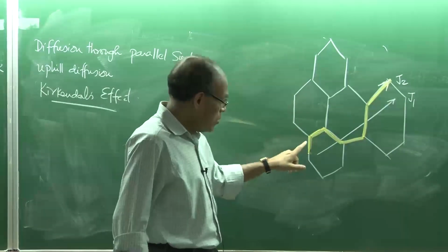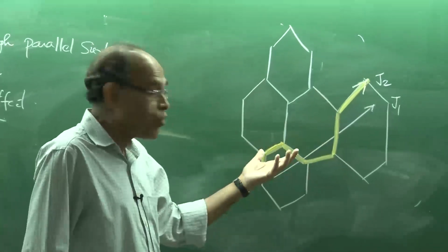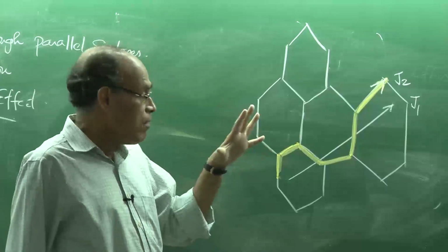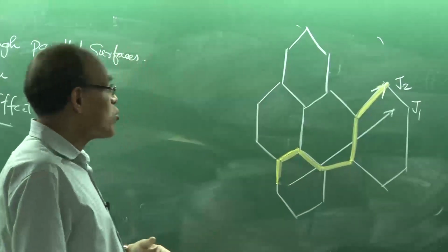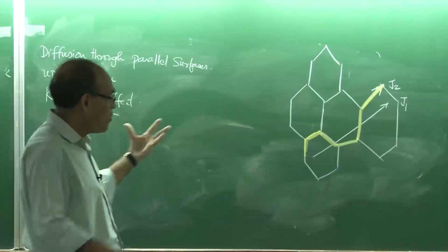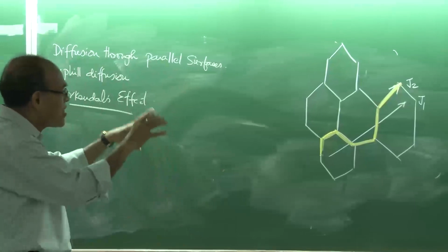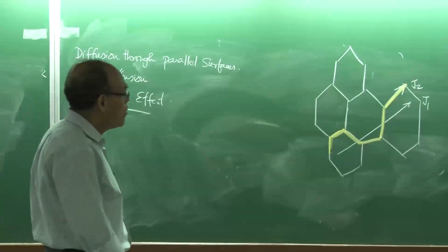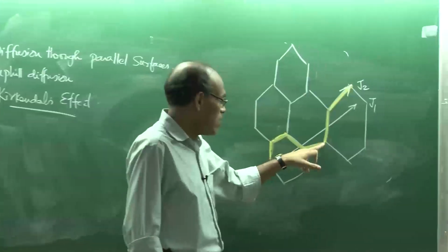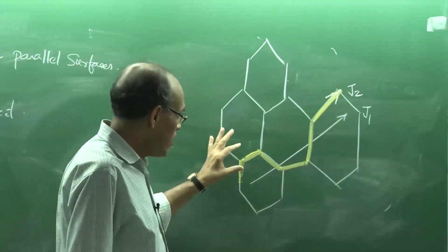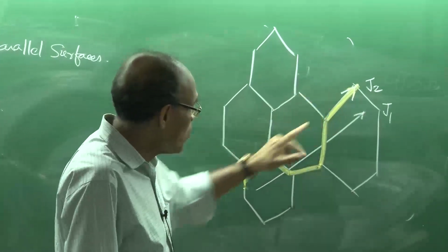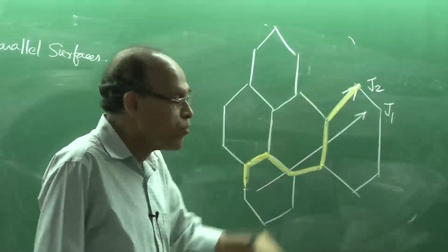Now, the grain boundaries, as you all know, contain defects, and we know that diffusion is promoted because of defects. We have interstitial defects, vacancies, etc., which promote it. Had the material been perfect, with every lattice site occupied, there would have been virtually no diffusion at all. So, because the grain boundaries contain defects, even though the path seems longer, the diffusion is expedited through the grain boundary.